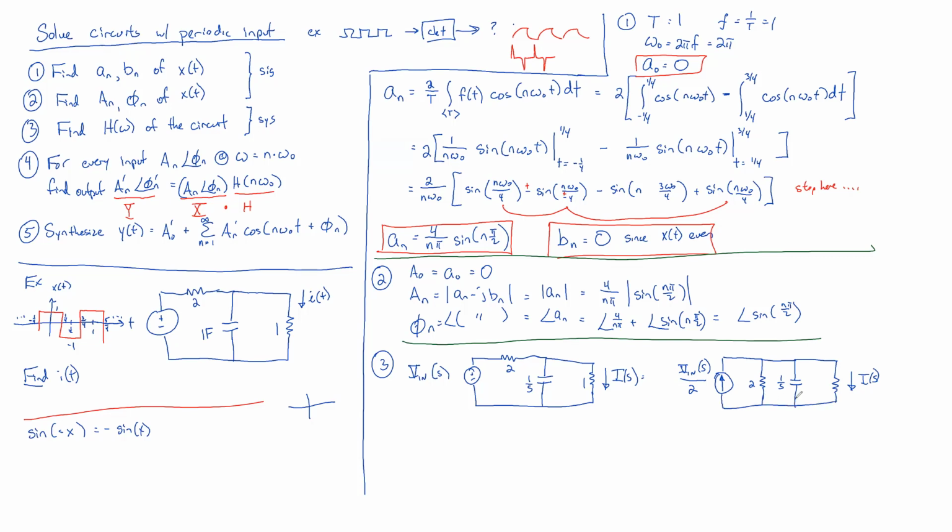Now, although there is a formula to do all this in one shot, you end up with nasty reciprocal signs, and that can make algebra tricky. So I'm going to instead find these 2 guys, which are in parallel, and simplify that. I'd say 2 in parallel with 1/s is equal to product over sums.